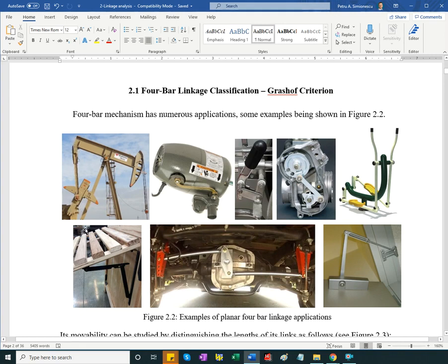So continuous rotational input of the crank makes the output link oscillate. This one too is crank driven, but the crank is floating, so it's an oscillating fan. There's a 4-bar there, but the power is delivered from the fan motor to the actual coupler. Coupler is the link that is not pin jointed directly to the ground.